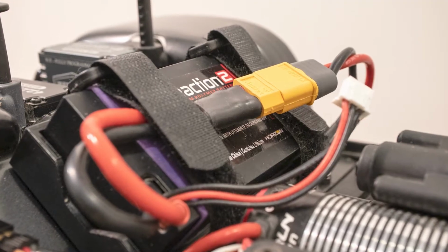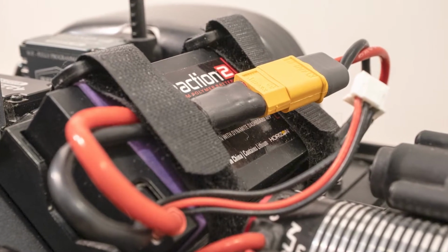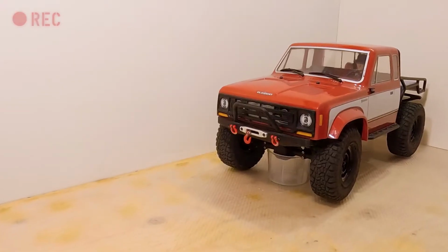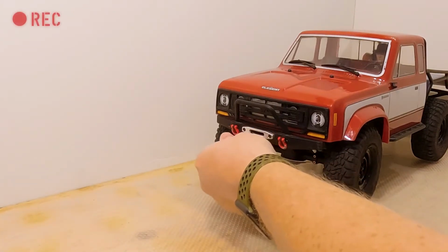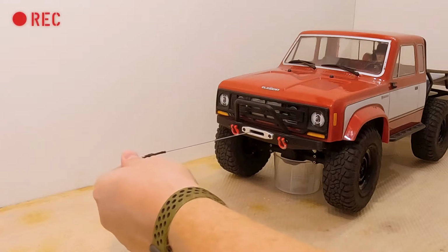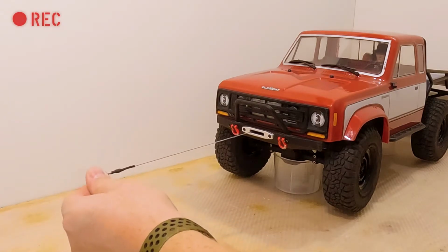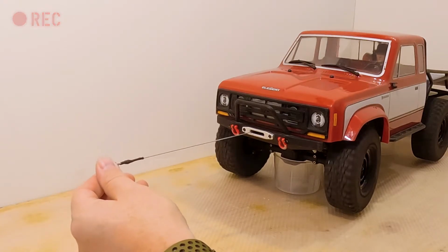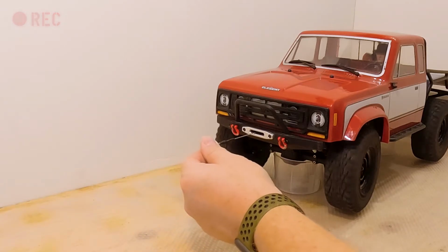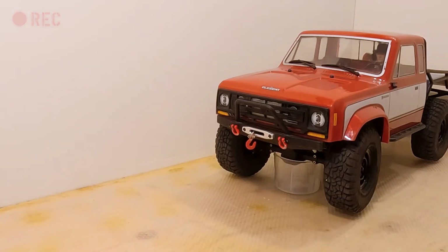You can now power on the truck, but make sure the wheels are off the ground. Click the C input in the off direction to disable the mix. Spool out some winch line with your usual winch control. The wheels and the throttle monitor indicator should not move. Now, click the C input in the on direction to enable the mix. Spool the winch line in with your usual winch control. The wheels should rotate in the forward direction.